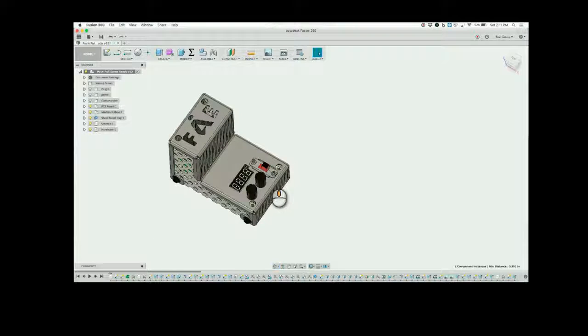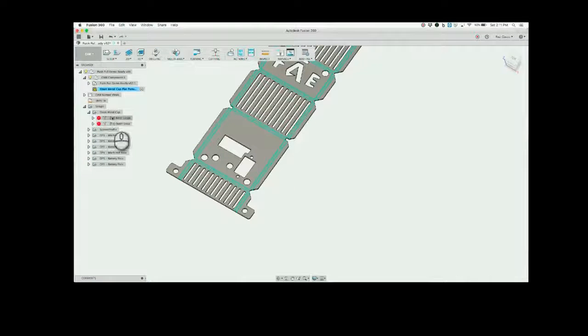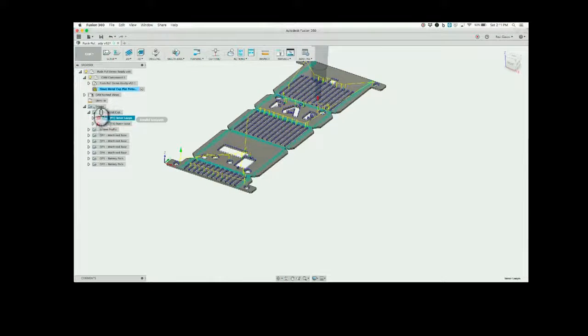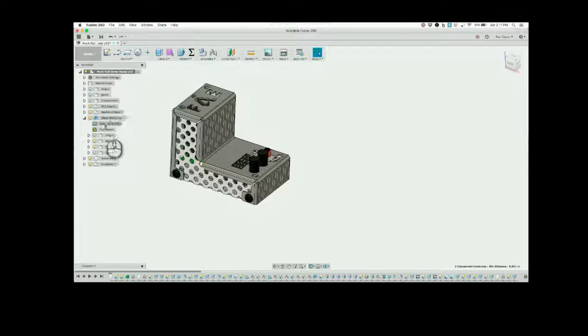And then we'll see now, if I go to my sheet metal component there, we can see that my flat pattern's out of date. So I'll go to CAM, everything still looks like it's where it should be, but we know that flat pattern's out of date. So our manufacturing engineer already has a red flag there. So we'll update the flat pattern.